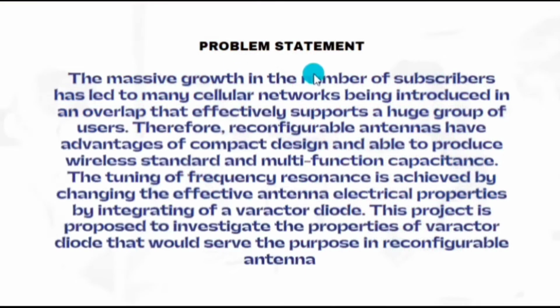So the problem statement is the massive growth in the number of subscribers has led many cellular networks being overlapped that effectively support a huge group of users. Therefore, the reconfigurable antenna have advantages of compact design and able to produce wireless standard and multifunction capacitance. The tuning of frequency resonance is achieved by changing the effective antenna electrical properties by integrating of varactor diode.